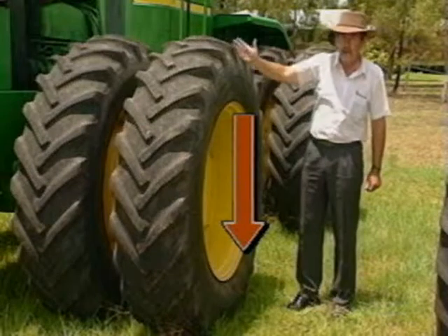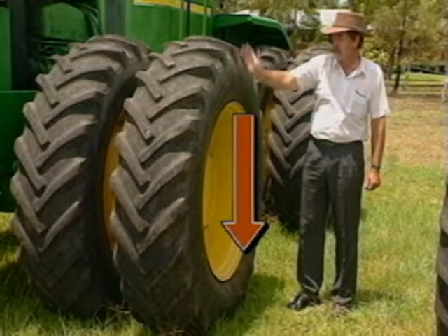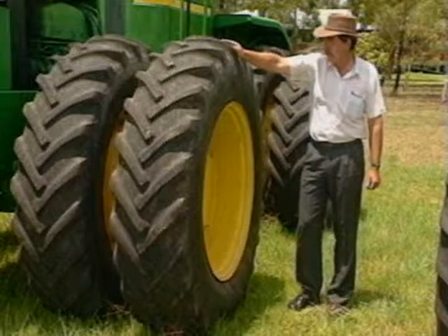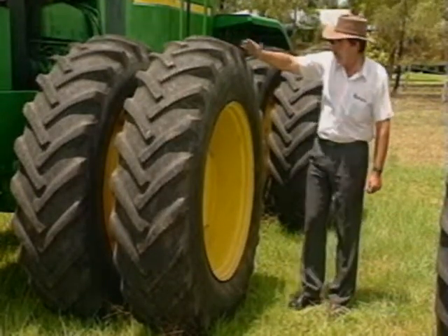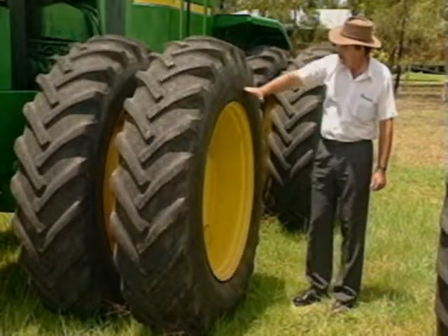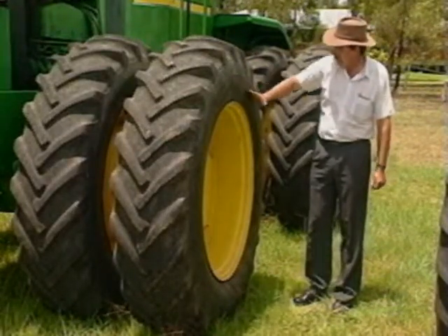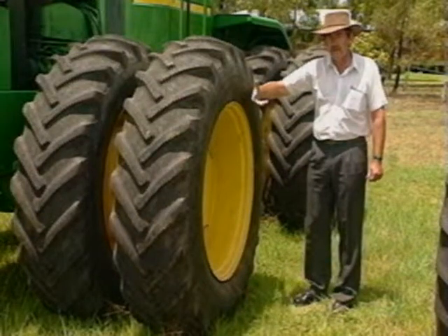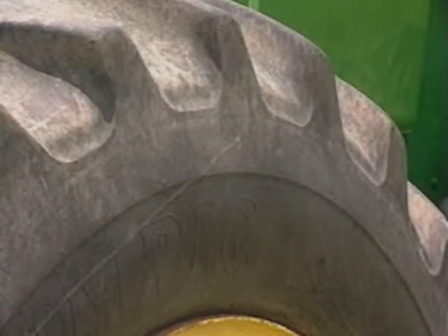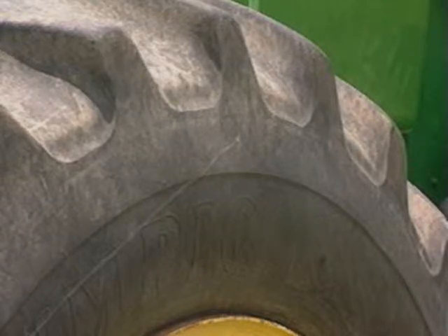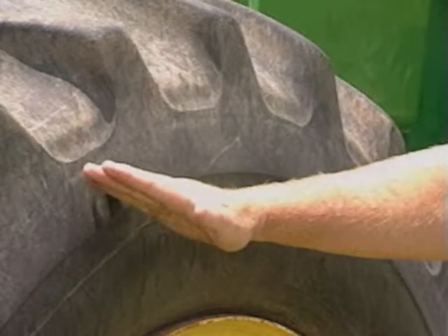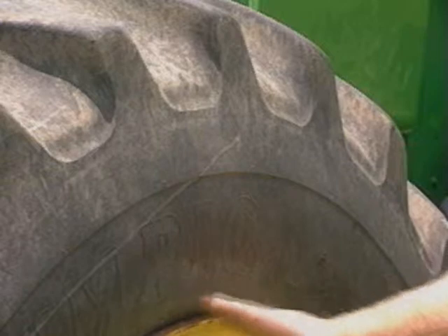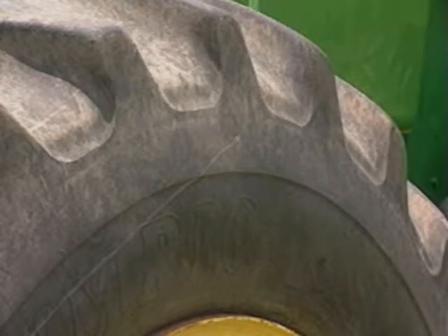So if we get back to the first point, the most important consideration is the vertical load on the tyre. Now that's the load bearing vertically down on the tyre, which we've calculated by weighing the tractor and setting our tyre pressure accordingly. The second is the tangential pull on the tyre, or the torque loading on the tyre, where the rim is trying to turn its way out of the tyre. This is an important factor as far as the integrity of the sidewall goes, and we can see that if we're overstressing the tyre, we start to see a crease at 45 degrees down the side of the tyre. These can ultimately lead to total tyre failure.